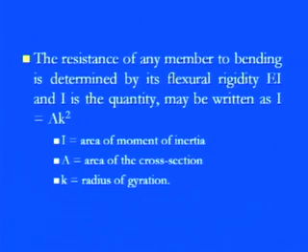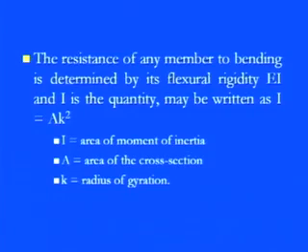Again, we have to be very careful about what exactly the shape of this object is, because based on the shape we know how the fibers or layers of fibers are set up. If you apply load, let us say compressive, tensile or shearing, then we know how these fibers will react because of the shape. So shape is also an important aspect, which we compute in terms of I, which is nothing but the area moment of inertia. The whole term E into I is known as the flexural rigidity,